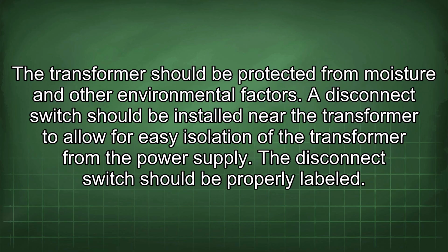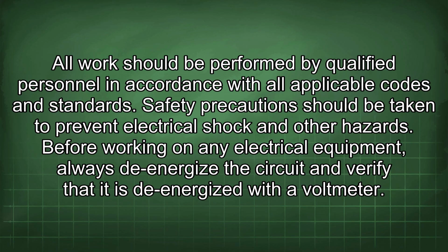A disconnect switch should be installed near the transformer to allow for easy isolation of the transformer from the power supply. The disconnect switch should be properly labeled. All work should be performed by qualified personnel in accordance with all applicable codes and standards.